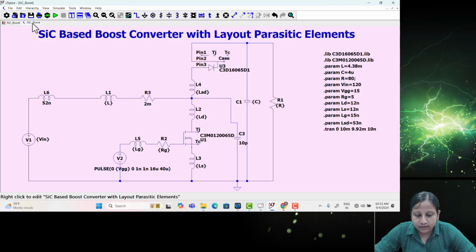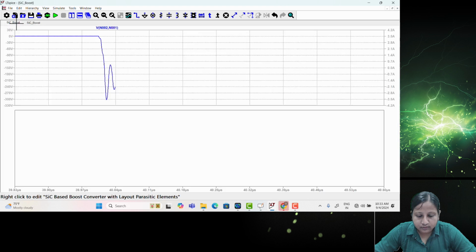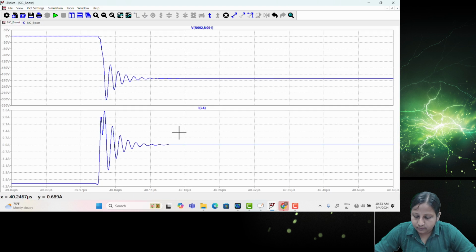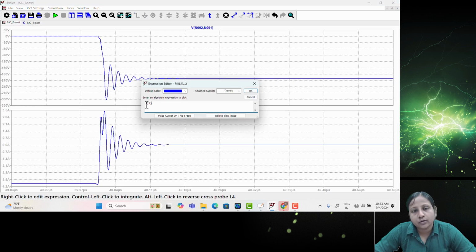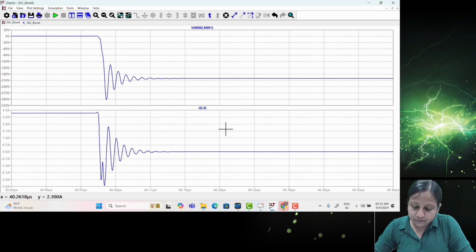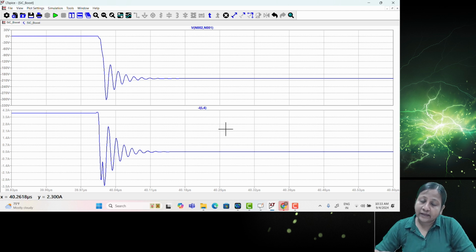And the diode current, this also has similar noises. So these are the different kinds of noises which you will also be able to see in the practical circuit. If you see this, then you have to go back to the analysis of the circuit to understand what parasitic components may be present, and add those again in the simulation to understand the circuit operation better.